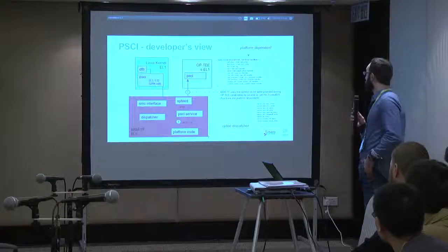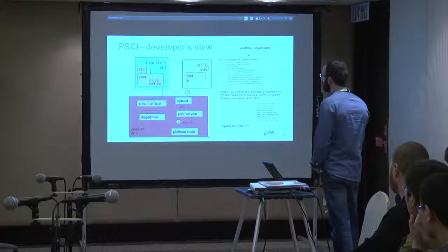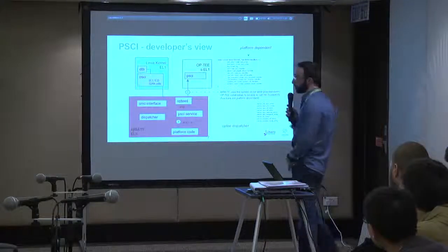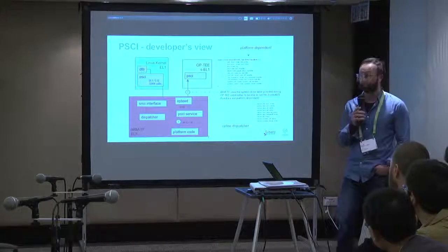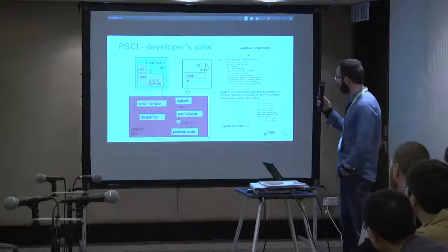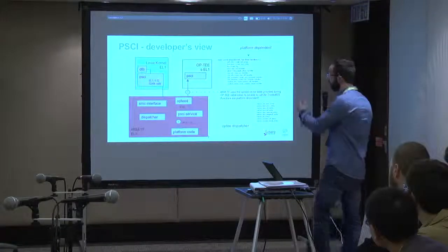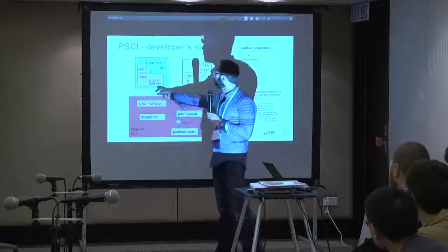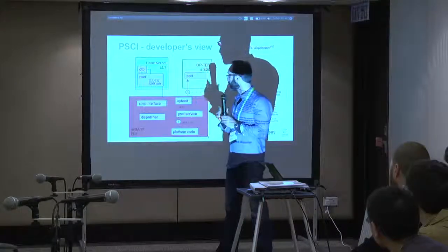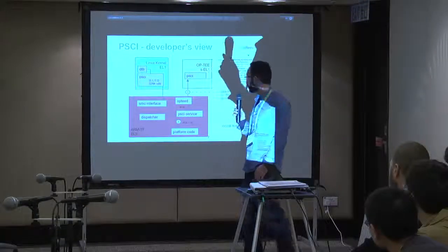So from the developer's point of view, the presence of PSCI is reported using the firmware tables. In the Linux kernel, you've got the device tree representation. You specify the version of the interface that you are supporting, and you've got 32 or 64-bit calls.